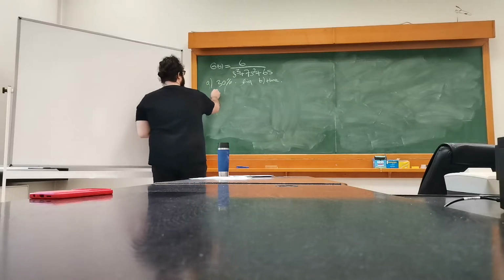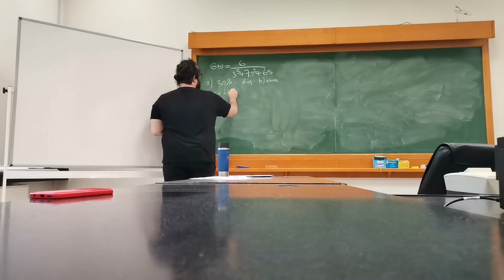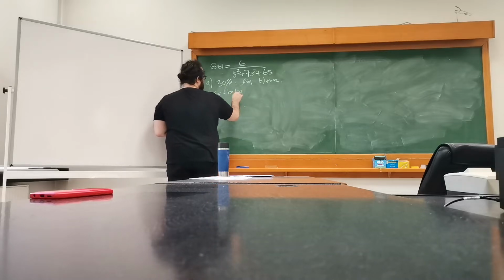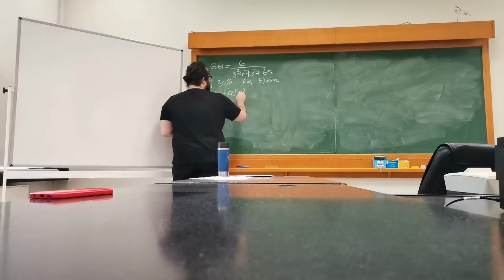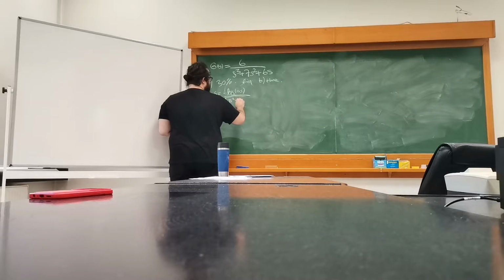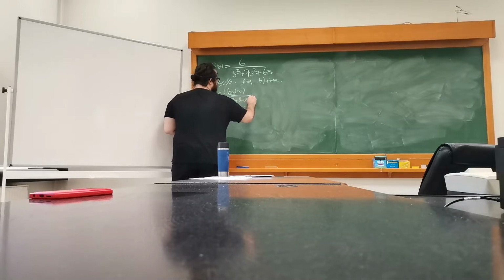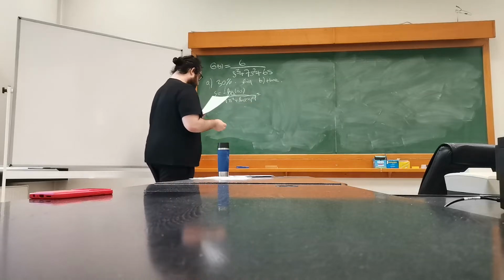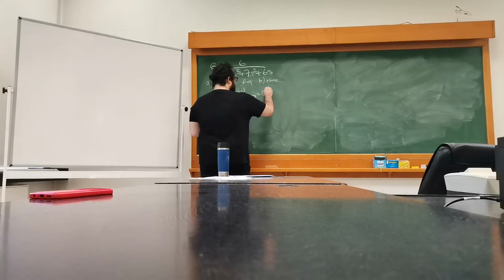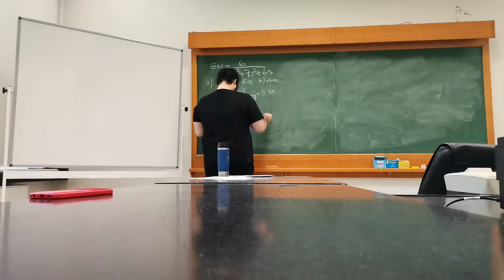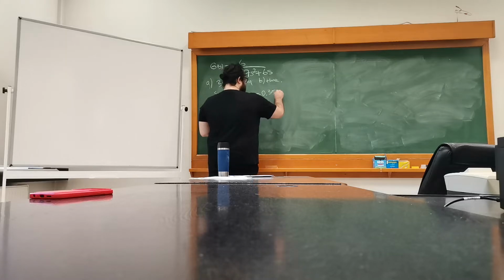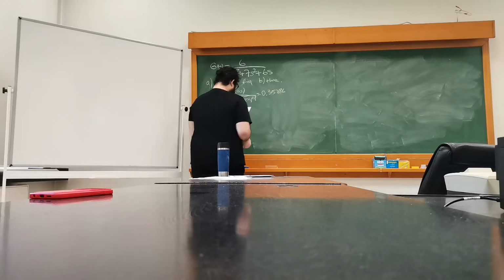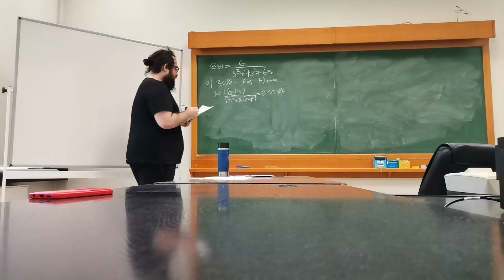Well, the first step is to use, again, minus log overshoot, or basically log E. You can also write it down as ln overshoot divided by the square root of pi squared plus ln overshoot squared. This will give you a specific zeta value, which in our case is 0.356786. So that's the zeta value that you look for.